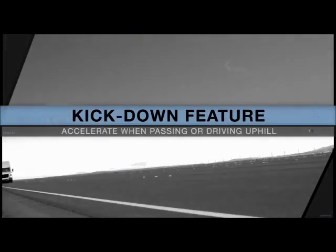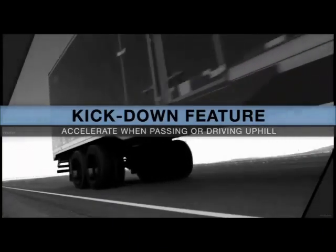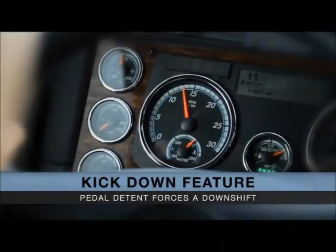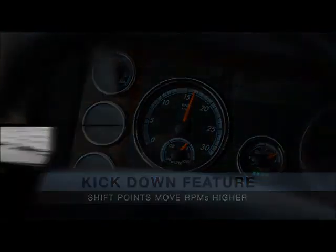This is why the off position is also the auto position when cruise control is set. The DT12's optional kickdown feature enables you to increase acceleration when passing or driving on uphill grades. After reaching full throttle, a detent in the pedal will allow you to force a downshift and allow the shift points to move higher in the RPM band.